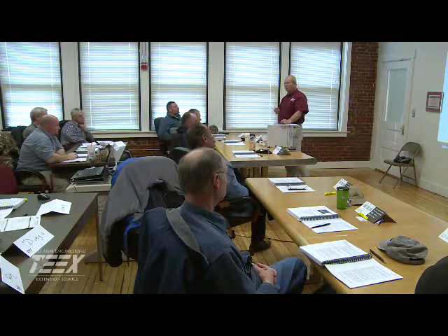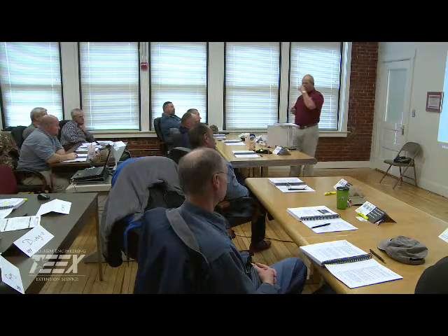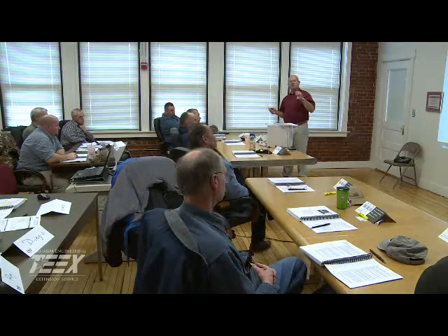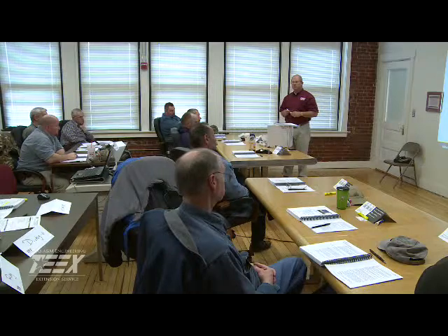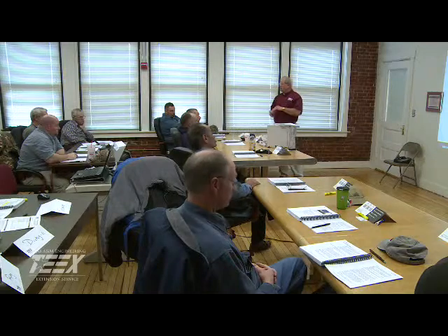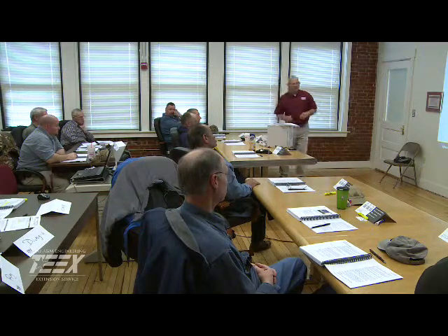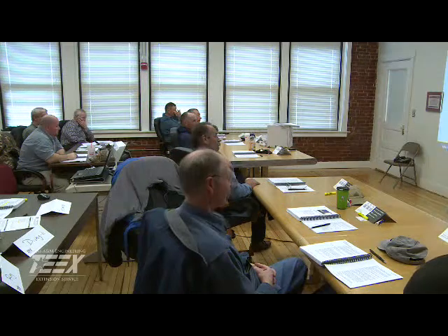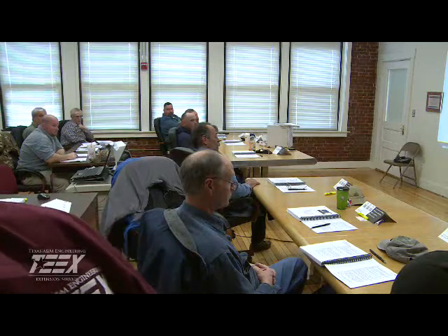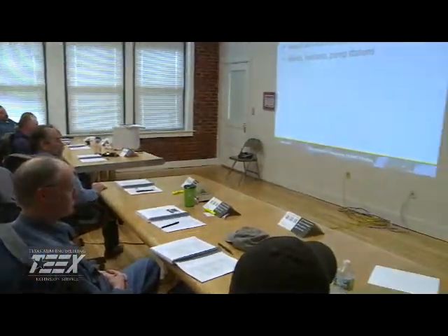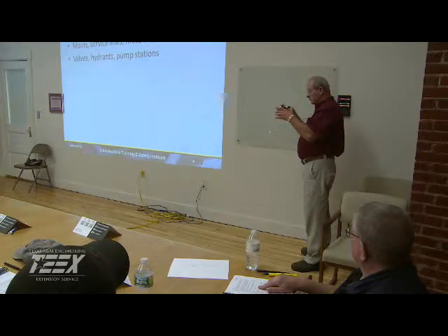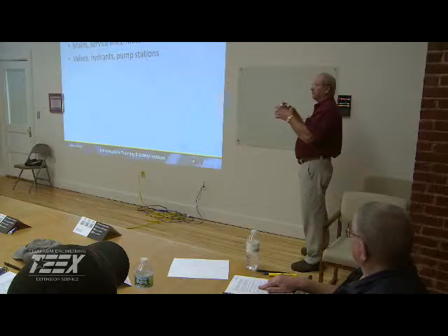But when it comes to flow control, there's many types of flow control valves. We have what we call special valves, like a check valve. A check valve only allows the water to flow in one direction. Then we have like altitude valves. An altitude valve opens and closes based on head. Now, again, over here on this board, I'll show you. An altitude valve has a pilot valve that recognizes differential pressures, okay? And actually, it's a globe valve that has a pressure reducing valve built in and a differential pilot.